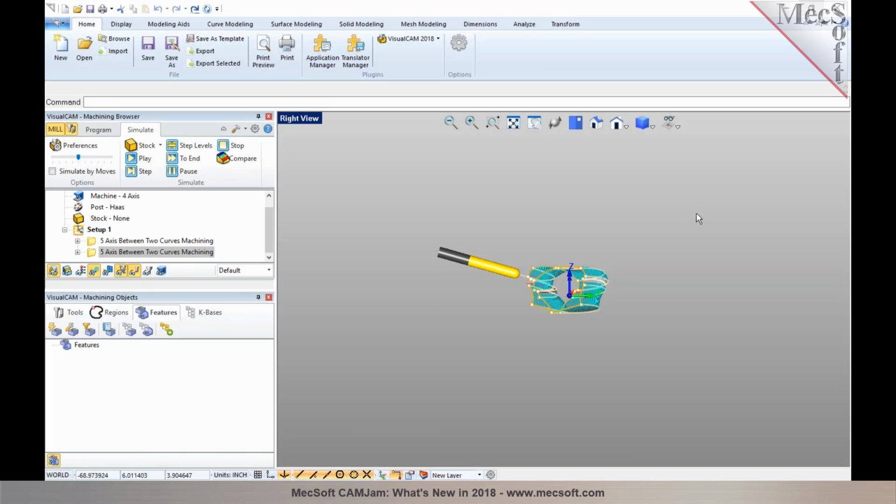Yeah, this actually opens up an entire class of parts that you can machine. Things like what they're showing here, twisted handrails for staircases and things of that sort, chair handrails. A lot of furniture makers use this kind of geometry, and you don't need to have a 5-axis machine. You can machine these now with these options that we have put in for, I believe, the 5 methods there in the 5-axis panel. So quite a few methods for you to utilize on your 4-axis machine.